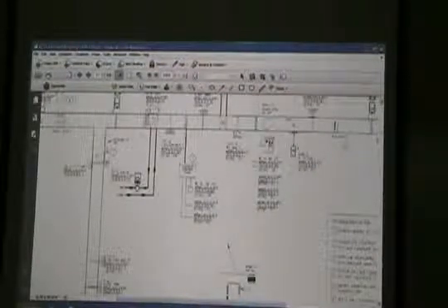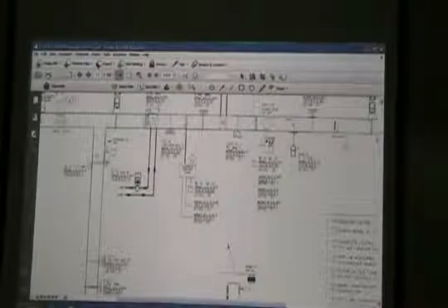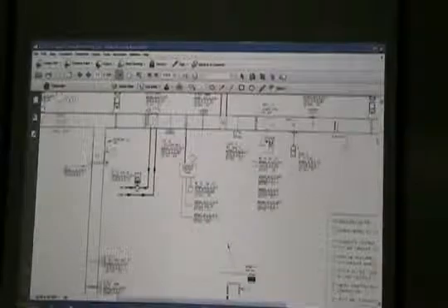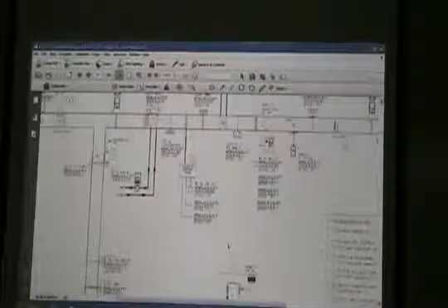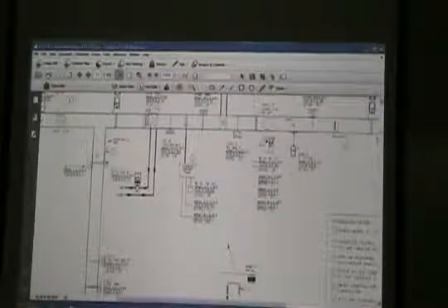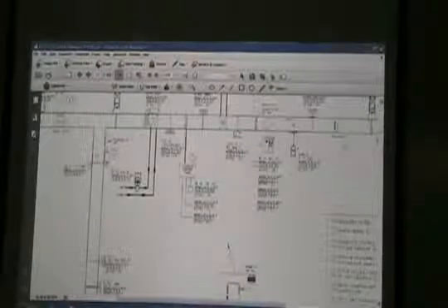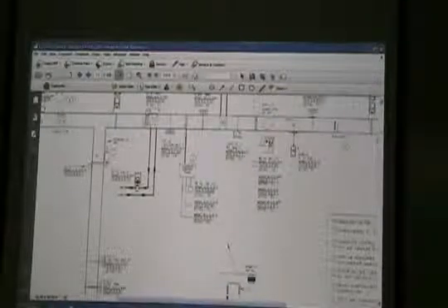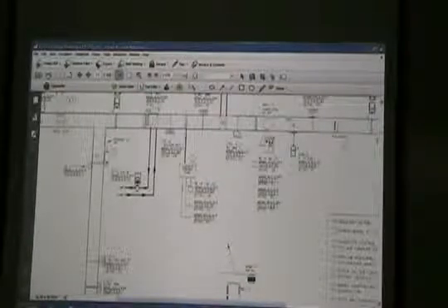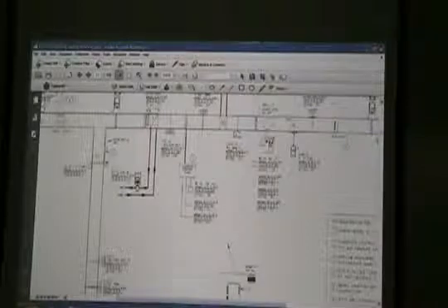Still can't read that. It's a humidifier enabled. E, enable, S, status. What's the A? That's an alarm down there. The S is probably the signal. Signal 2. Well, I'm sure that we'd actually take control of that humidifier. This is an electric humidifier. If we're going to maintain the return air humidity, we're going to have to be controlling the output.